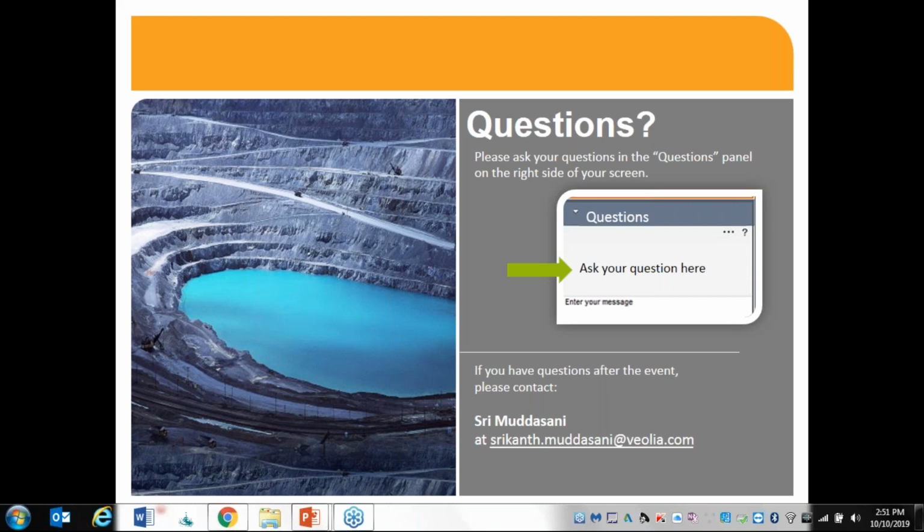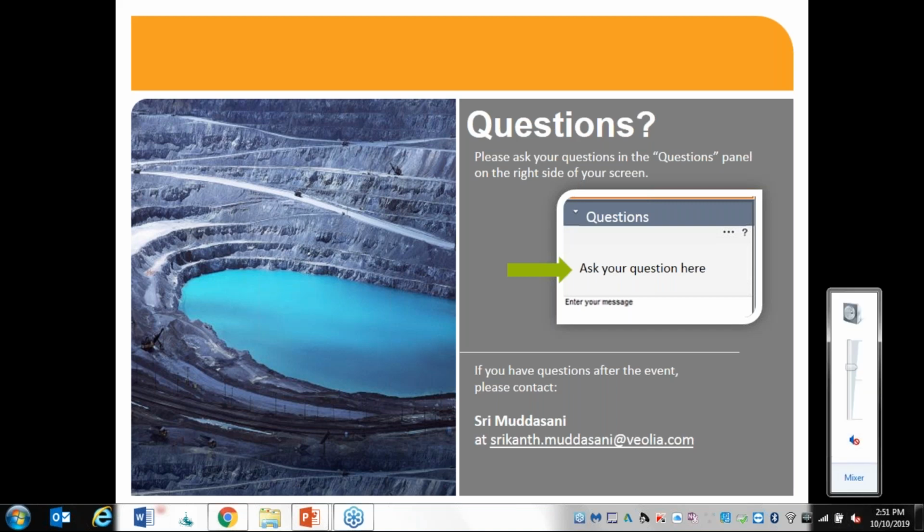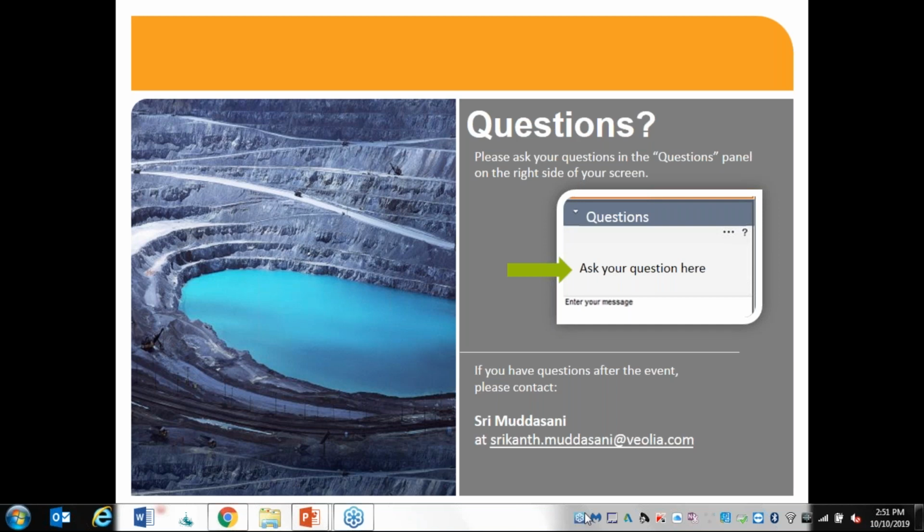Okay. We've got time for just a few more questions here, but one that just came in is, what percentage solids do you get with dewatering of the sludge? In the pilot study, we were able to get down to 20 to 30% cake for the ettringite solids. On calcium sulfate, you can go up to 40 to 50% easily.